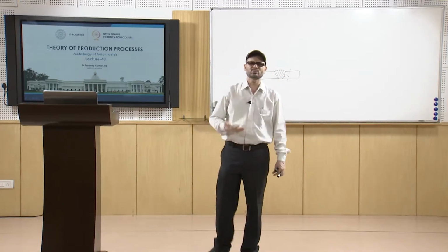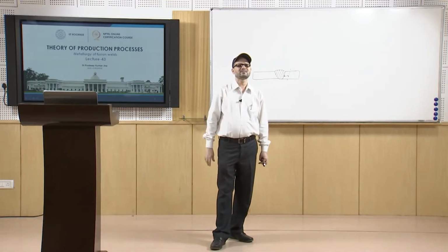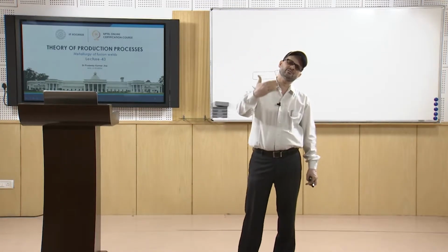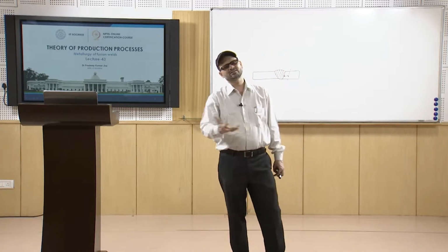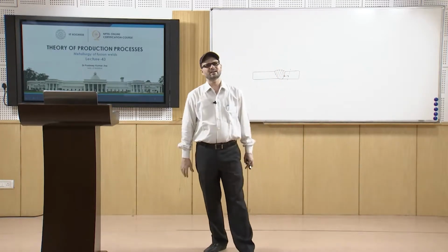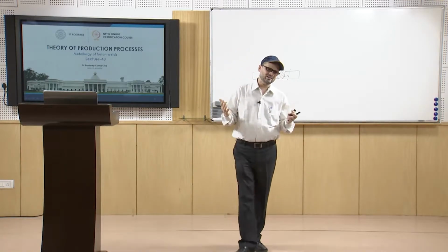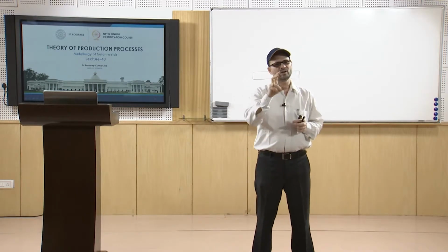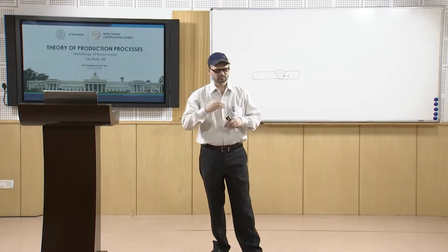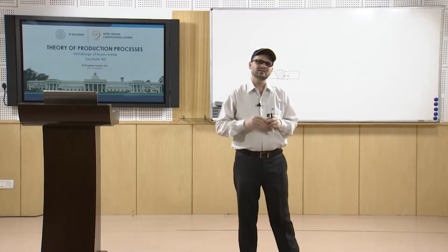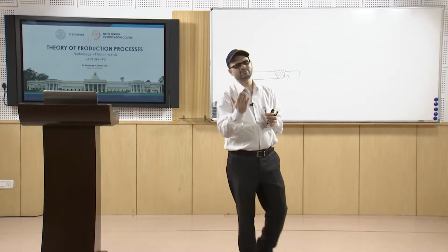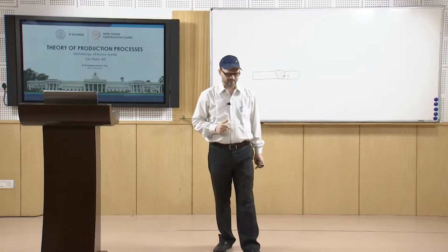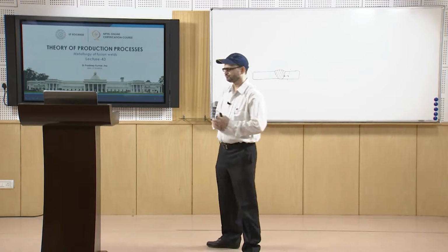That again depends on the temperature rise in that area. If the temperature rise is not enough to promote any kind of transformation, then that zone is called the unaffected base material zone. All the zones where there has been an effect because of the temperature or thermal cycling are known as the heat affected zones. And then you have a zone which is solidified, which has a cast type of structure, and that is known as the weld metal zone.